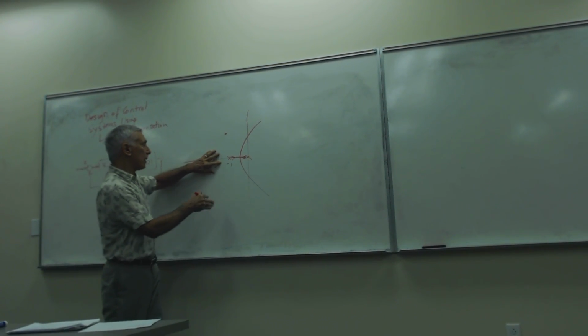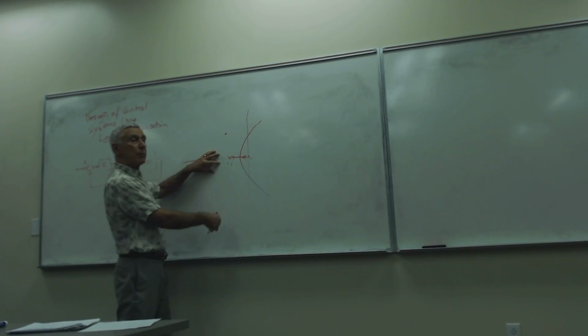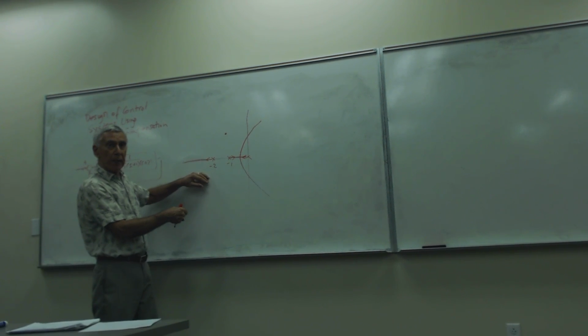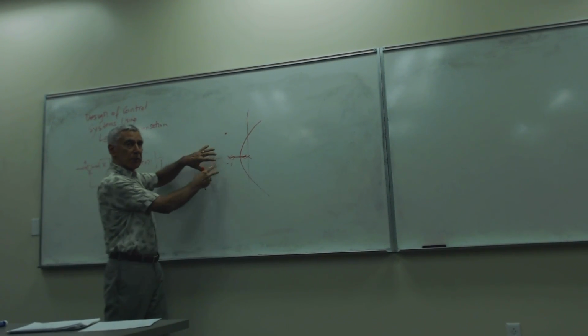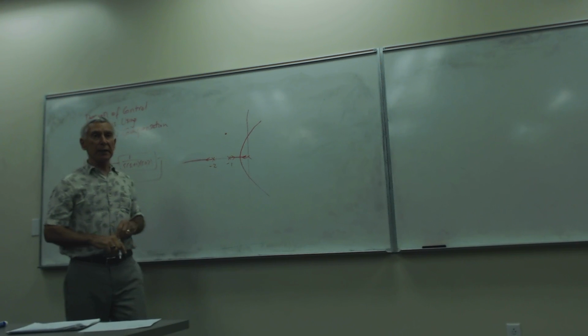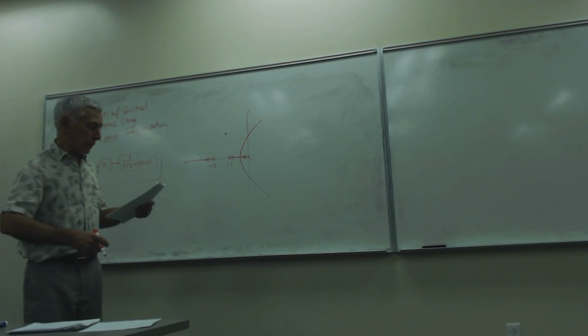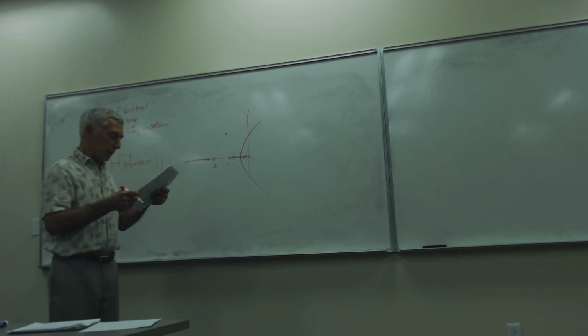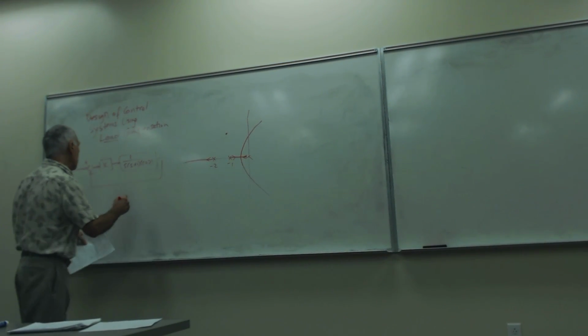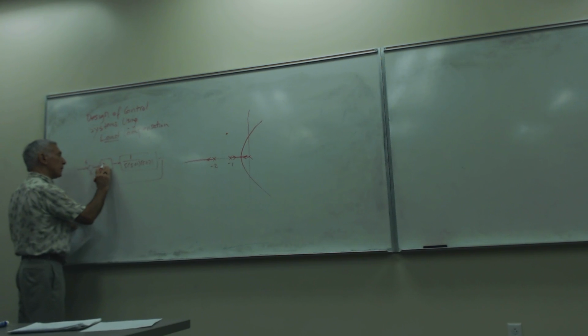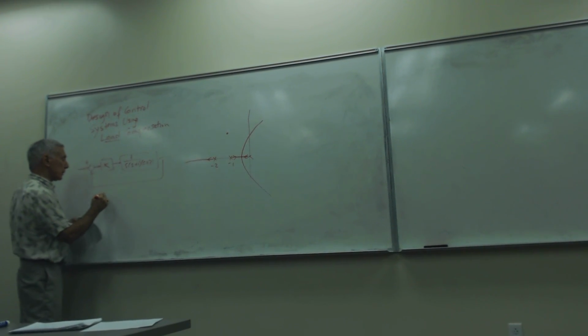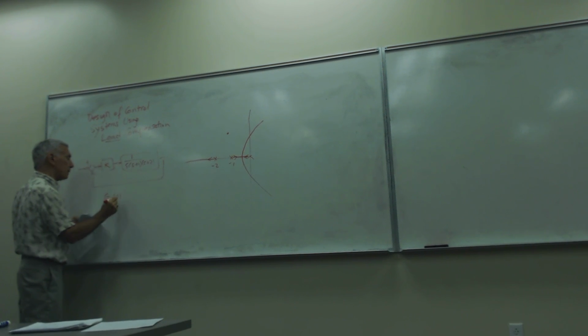Just as we were saying, if you didn't have that pole, the locus would be vertical in the middle. If you put the pole there, it repels it. If you put a 0 there, it'll attract it. So we want to talk first about the lead compensator. In general, this is GC of S. Just leave it as K, but in general, it's GC of S.